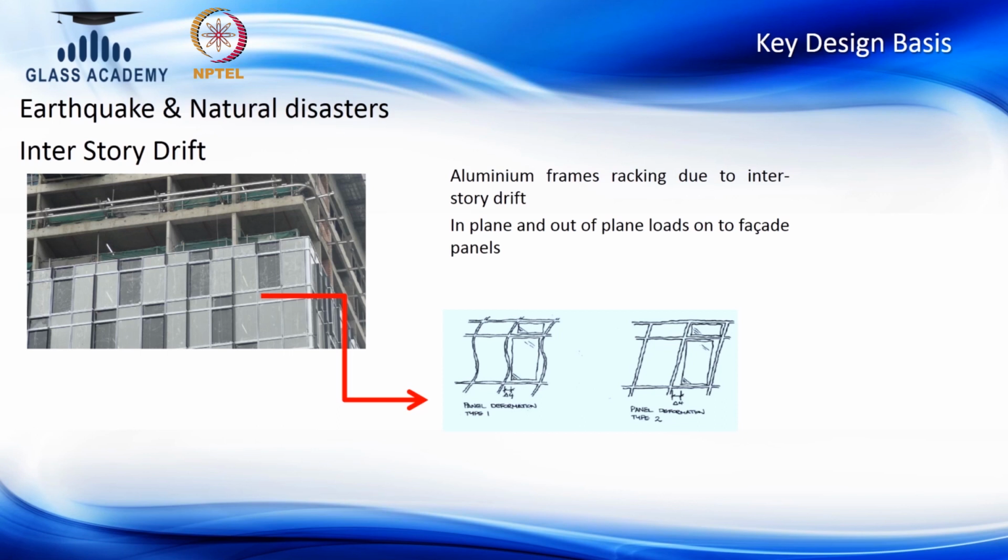But this building sway, how will it impact the glass facade? If the framing moves, it could also give various modes of acceleration. The frame could have this kind of impact, or it may be linearly leaning towards this. So when the frame moves, it will put a lot of stress on the glass panel or any other cladding material which is holding this. As a structural engineer, they have to check this.